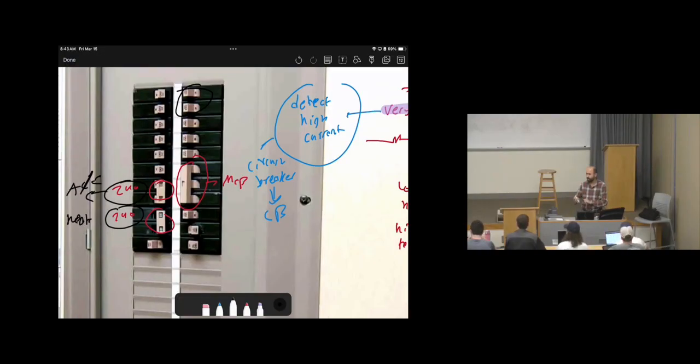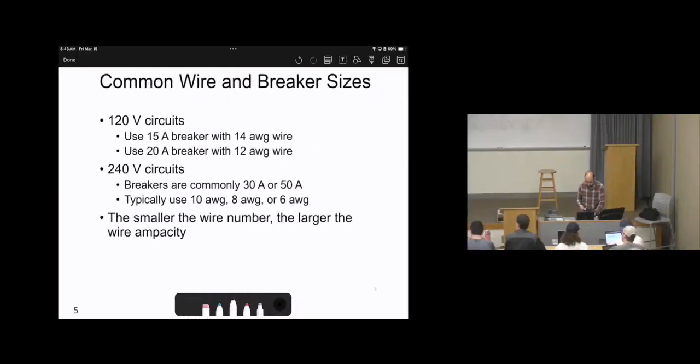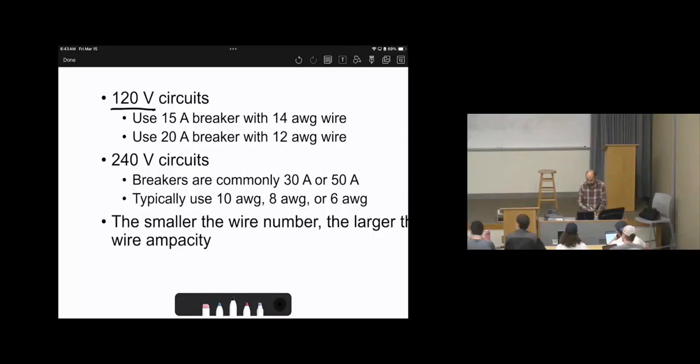So that's why sometimes the circuit breaker for each one can be different, even if it's the same 120, but this one has different settings. Each one has its own setting. Then, again here, when we deal with 120 volts, we have circuit breakers of 15 amperes, we have 20 amperes. Here, like 15, 20, maybe in Europe there is 10 and 15, so whatever here. 15 amperes, again, can be used for lighting.